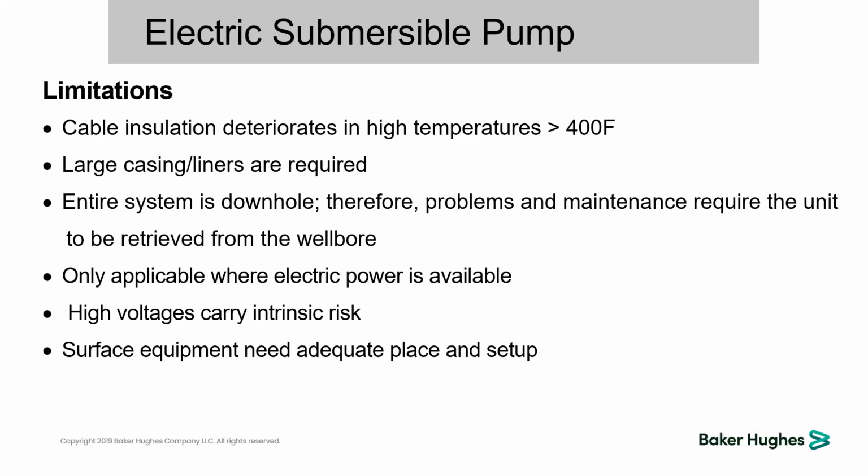Most of the ESP system is installed downhole. So if you need to make a well intervention, or pull the downhole equipment and install it again, you have to call a rig. Without a rig, you cannot retrieve and repair the ESP equipment. There are some applications of rigless ESP equipment, but nowadays it's only installed on high profile wells, such as offshore wells with high production, in order to have an efficient cost per barrel. But up to date, the ESP requires a rig in order to be pulled and repaired.